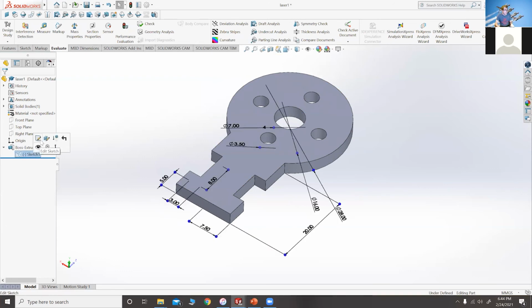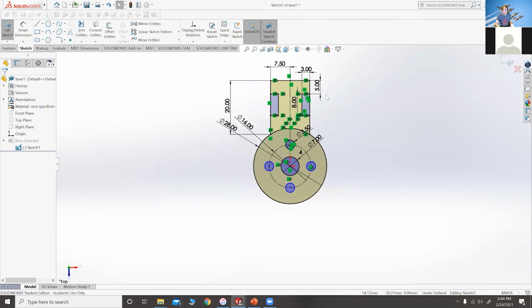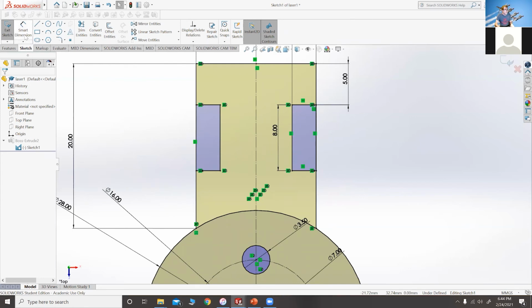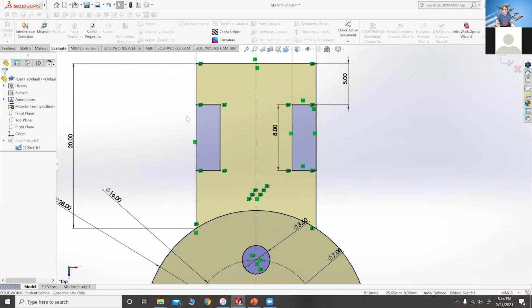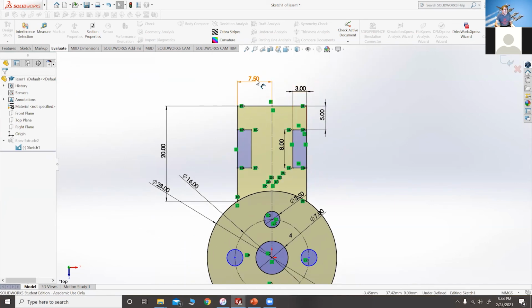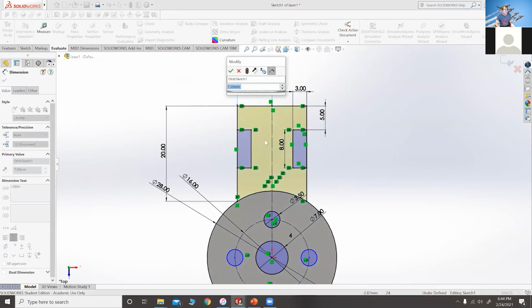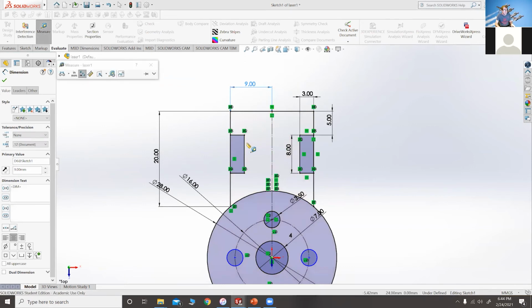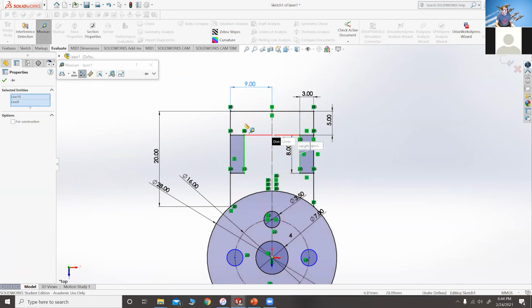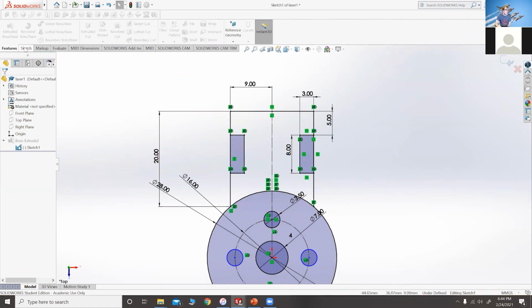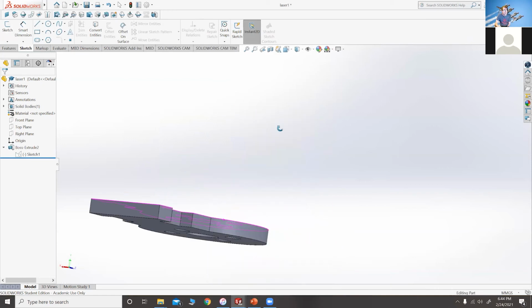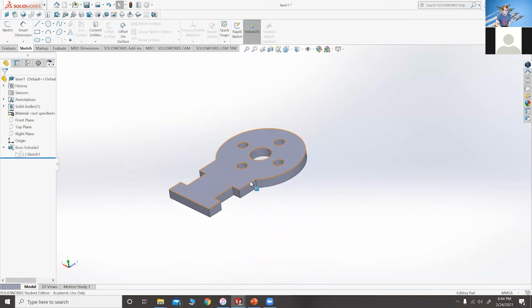So another thing that I briefly forgot is that, let's check this dimension here. So that's 9 millimeters. So we actually need to increase the size of this so that the internal diameter will be 12 millimeters. So it'll actually be 9 millimeters will give us 12 millimeters for that 12 millimeter spar. Okay, so we'll go back, we'll exit the sketch, it makes those updates. Great, so this is our part 1.